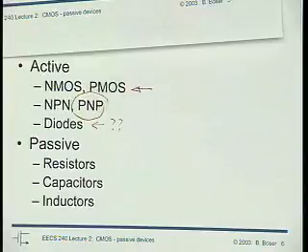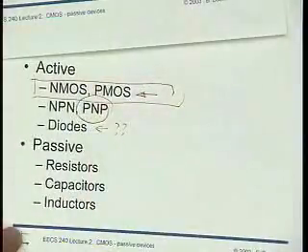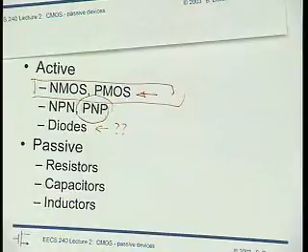Okay, so if you were a digital designer, you pretty much would say, great, what else, right? That's all I need. If you're an analog designer, you will say, well, gee, sometimes at least, again, for example, in a reference, a resistor is kind of handy, right? I kind of need it, and we'll see capacitors. We have just an unending appetite for capacitors in our circuits. We know in compensation circuits and so on, we're going to use them for everything, for all processing and for feedback networks. We're always going to use capacitors. So we somehow need those two.